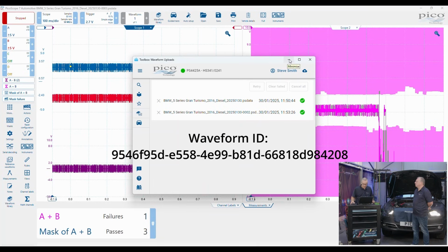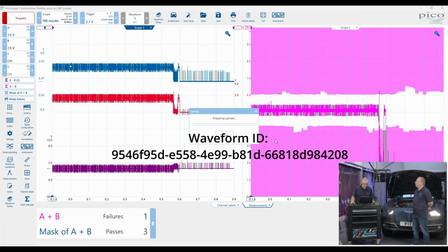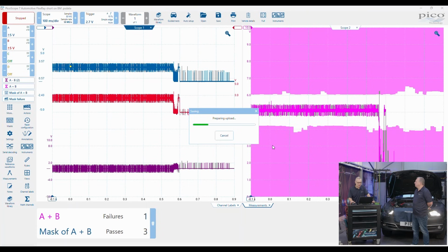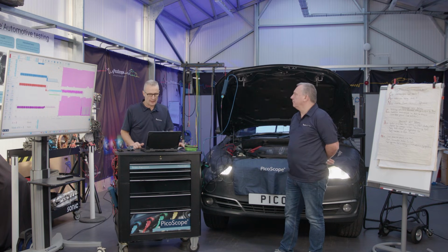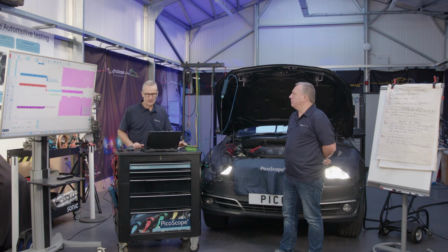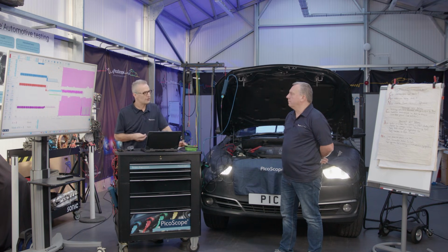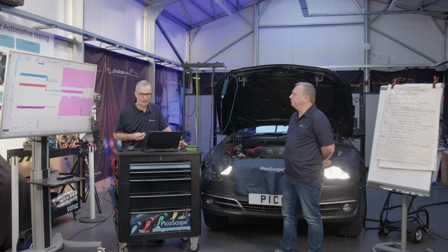All right, we'll have a little bit of a tidy up here because what I want to now do is just show you another tip that you may find useful. We're going to introduce a new probe now. This is our differential probe, and as the name implies, rather than measure reference to ground, we're going to measure across FlexRay high, FlexRay low.